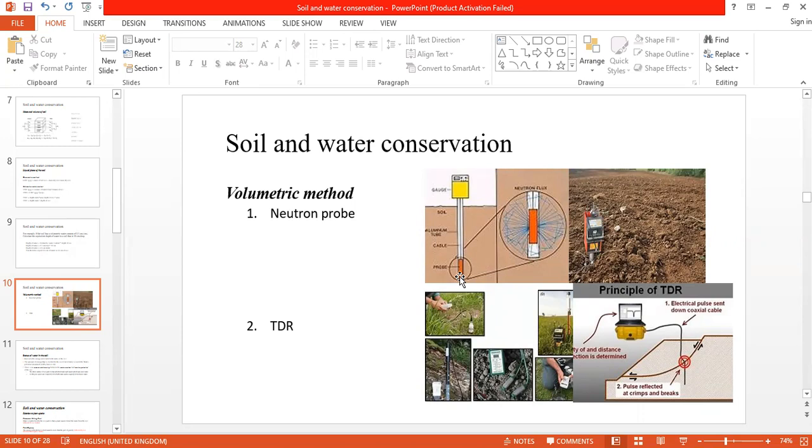Yes. So actually, what you can do now is create a simple linear equation with water content and speed. The water content will be your y, and your speed will be your x, in a linear equation. So if the speed is high, it means that the water content is low, because the neutrons just go fast, they are not obstructed by any water.